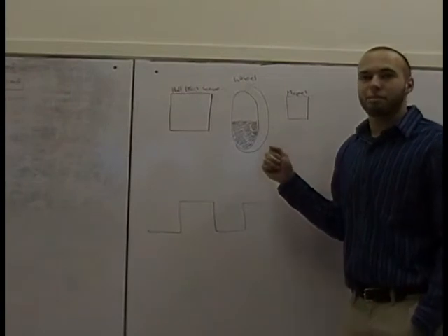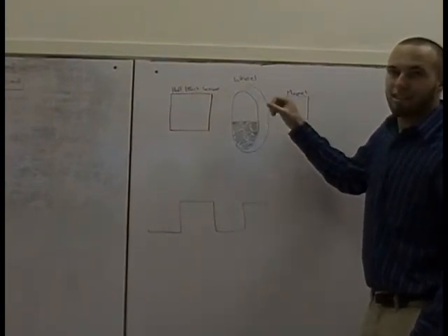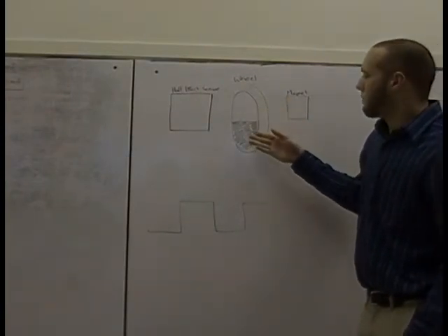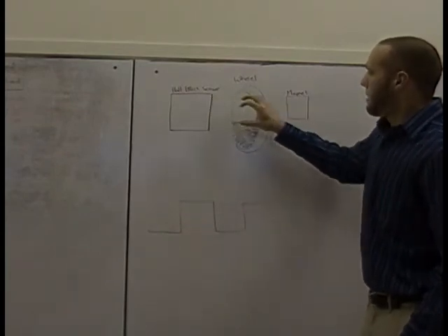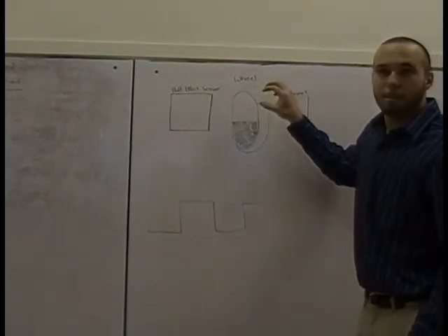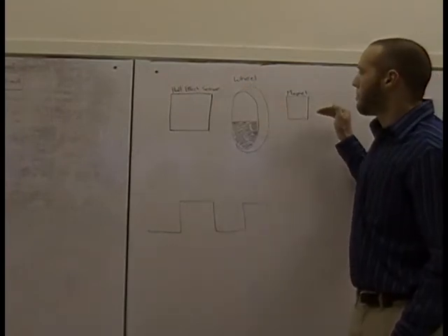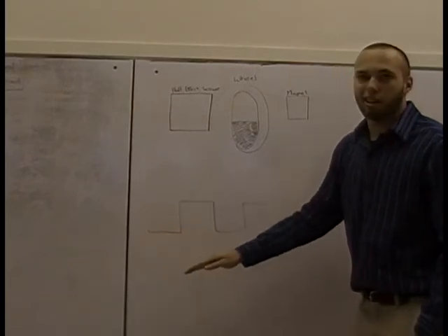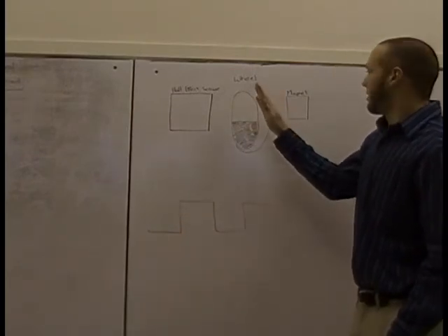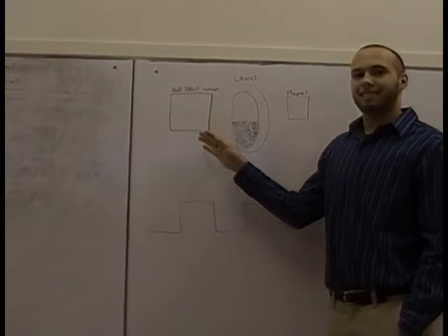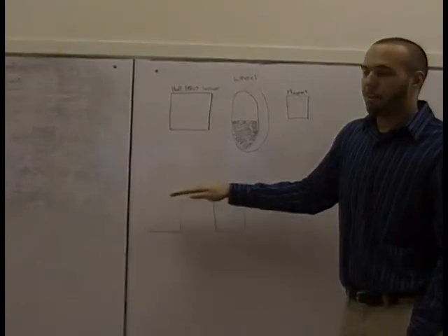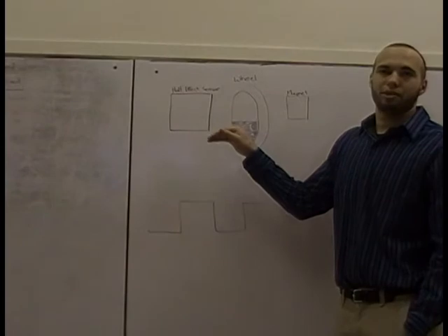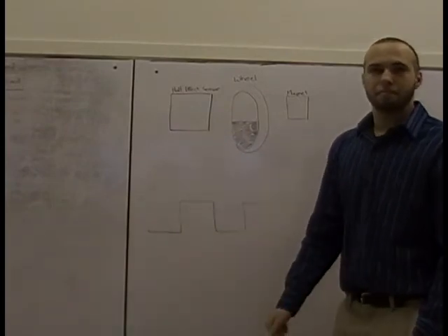To make this example simple, let's say half of the wheel, the inside of the wheel, is open, and the other half is some kind of metal. So every time the Hall effect sensor and the magnet line up with the open part of the wheel, the magnetic field from the magnet can get to the sensor, and that makes it output a digital low. And every time the metal is in between them, the magnetic field from the magnet is blocked and cannot get to the sensor, and it outputs a high, which is based off the reference voltage that you input into the Hall effect sensor.